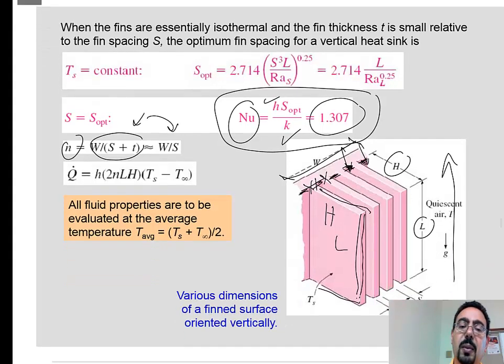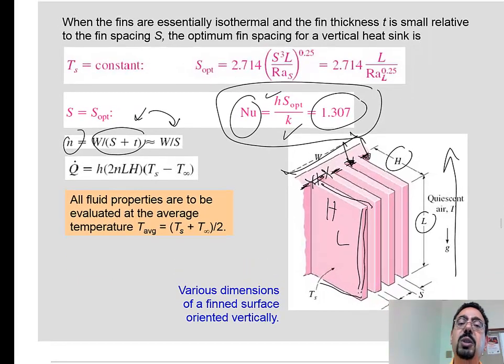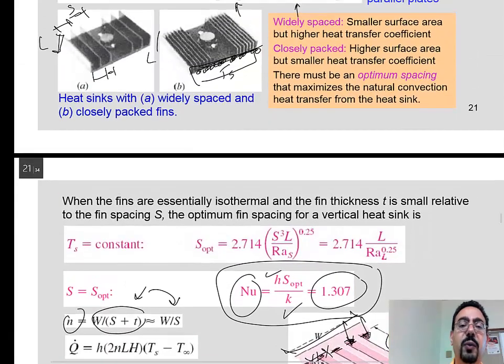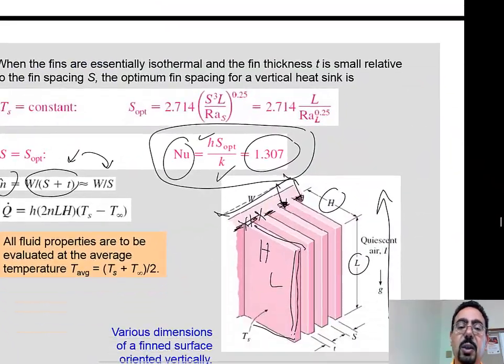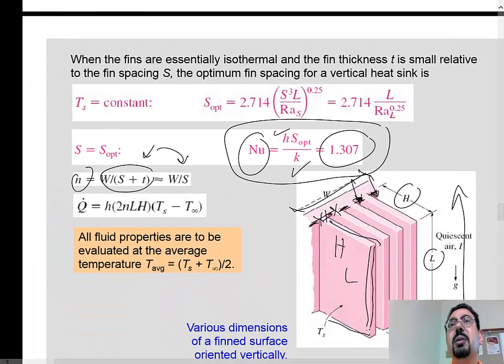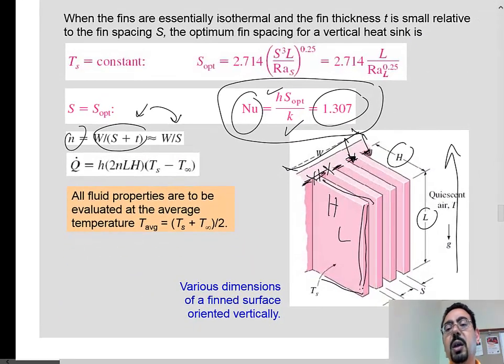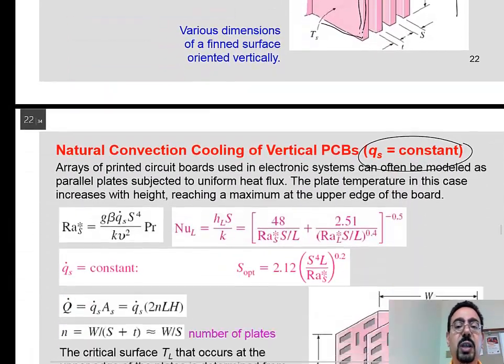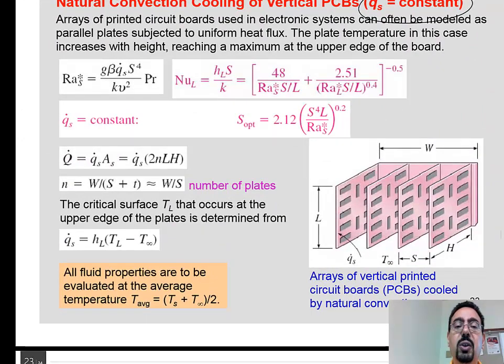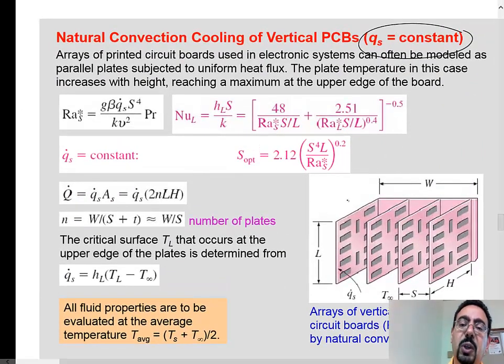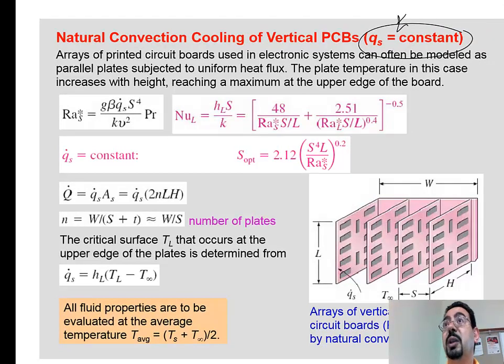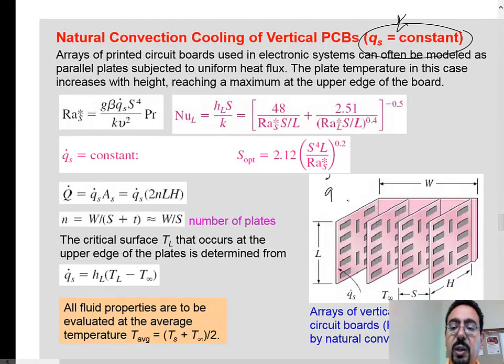Okay? And in either case, whether you are going with the maximum Nusselt or just a regular Nusselt, you will just come here and calculate the Q. H area delta T. All right. So this was the case for constant TS. Chances are, you don't know the TS. Chances are you know the Q. You know how much energy those guys are sending per unit area per unit time. Well, basically, you know the Q dot S, watt per meter square.